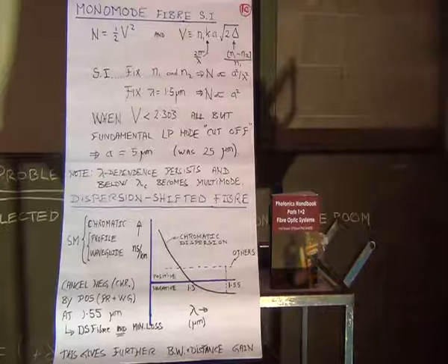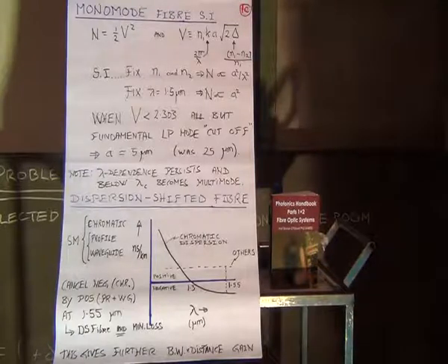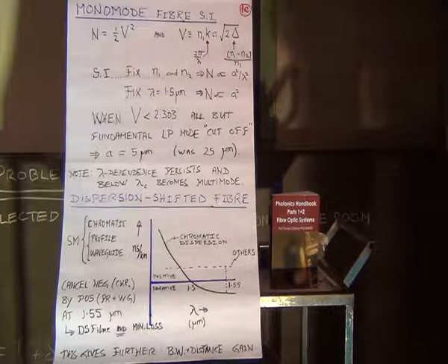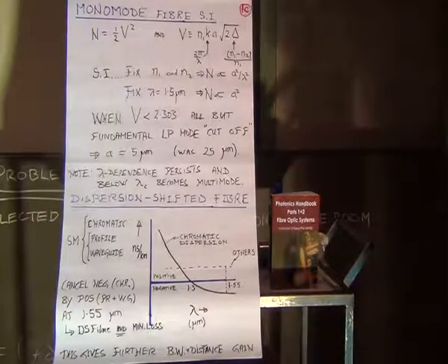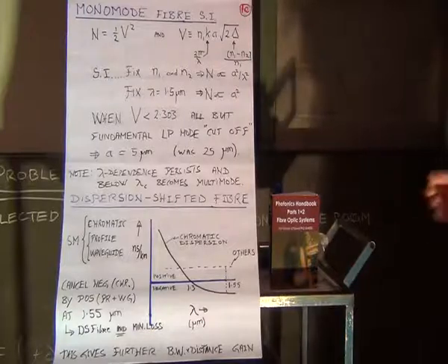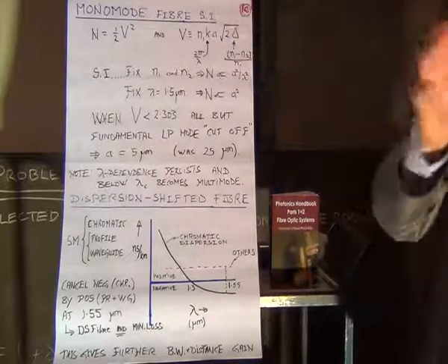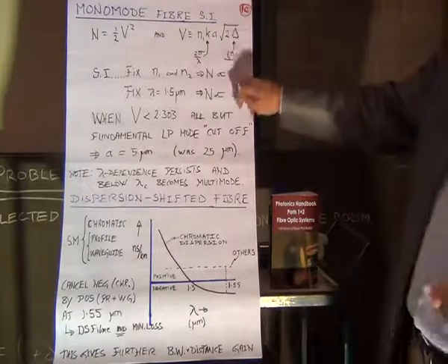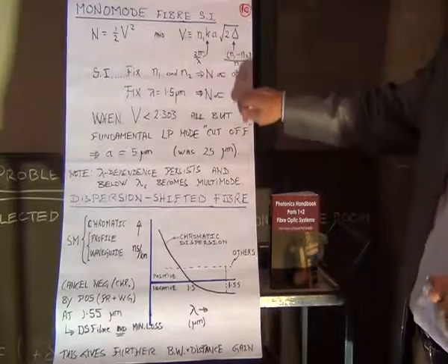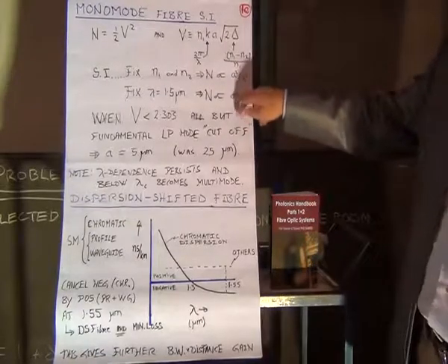The trouble was, it was difficult enough to align step index fibres with the precision required, not to mind graded index fibres. And now, in order to get a monomode fibre where only the fundamental mode travels, we would have to reduce the radius considerably.